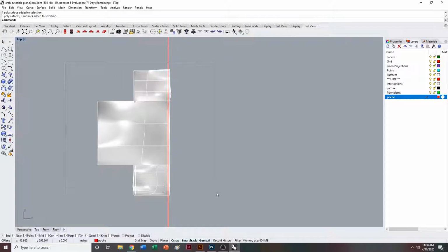So what I'm actually going to do is highlight everything and type in ungroup. Be careful when you do this moving forward, because there might be some stuff that you actually have to keep grouped. If that's the case, I usually make a copy and then ungroup everything in that single instance, just so I don't ungroup everything and have to meticulously go back through and readjust everything. So now I should be able to select everything on this side of the section cut. Beautiful, and I'm going to go ahead and delete that.